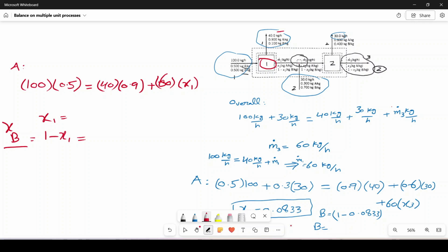The procedure is, first do the degree of freedom analysis on the overall system and then on each subsystem, and then try to solve from the overall system to minimize the number of unknowns, so that the points where the degree of freedom is higher than 1 can be reduced to 0.